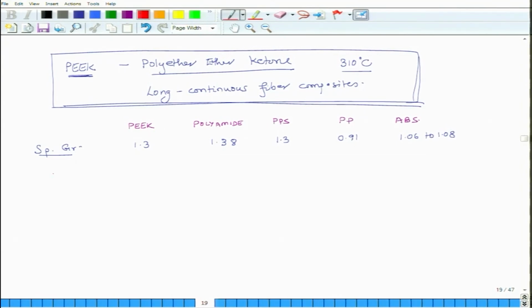The next material property is tensile modulus. And this is in MPa. So, 3300, 2800, 33, 1100. So, see, polypropylene, even though it is light, it is not that stiff, but for regular applications it works, and it is also very inexpensive. It is probably the cheapest matrix material available.